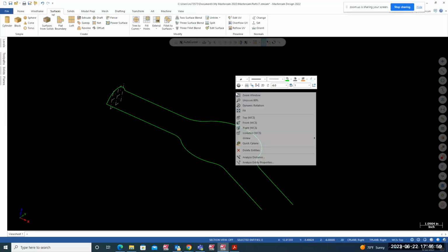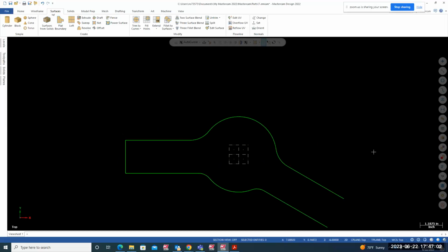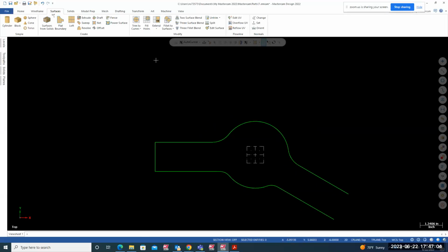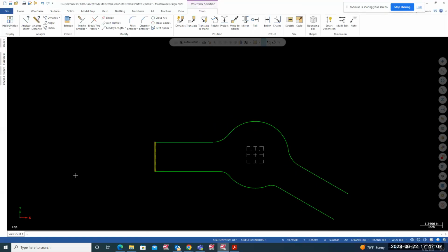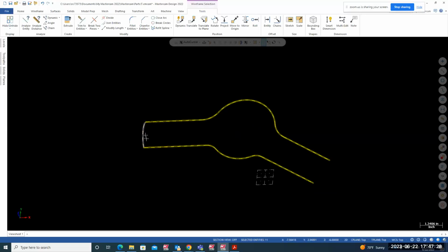So on that, if you look from the top view, these are your across contour and these are your along contour. Across and along. This is along. All these are across. So the way the sweep works, you pick up the across contour and that will sweep along with these rail right here.